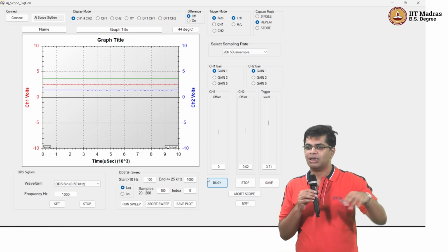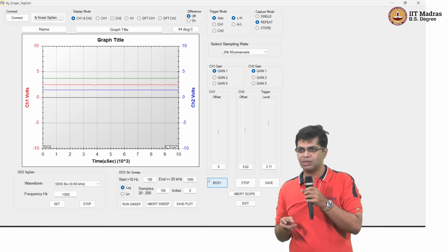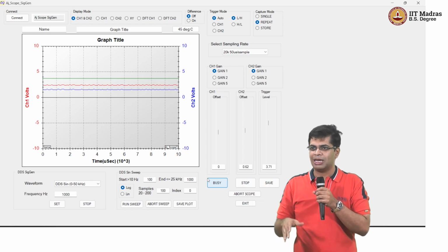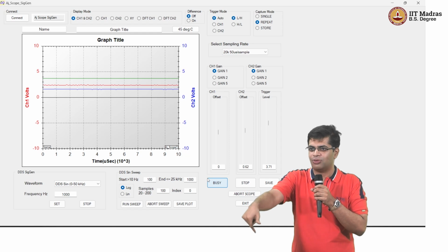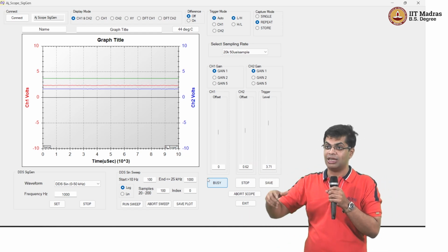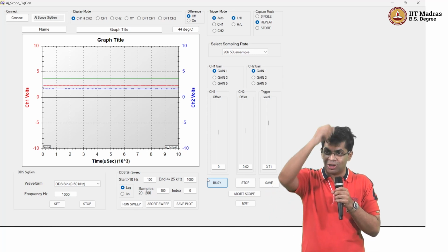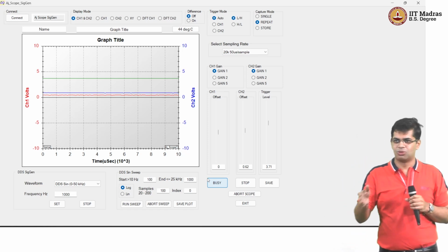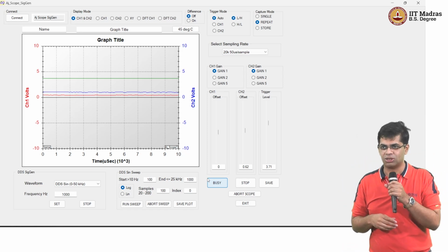The problem when you have 2 PCBs is it doubles our making time. For the robotic pick and place, assembling another few centimeters squared on the same PCB is easy. But if we have to assemble it separately, you have to reset all the alignment, components, mask, everything. So hopefully in the next 2 months we should have that.